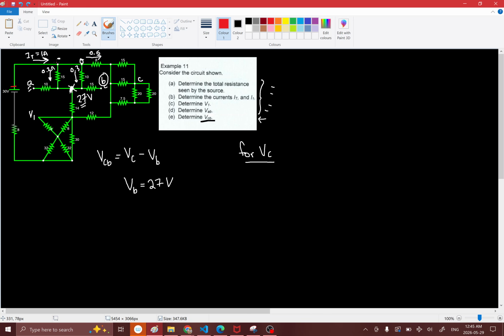All the current, which is a lot of current, can't just go through one resistor, so it will split itself among 2 or 3 resistors, that's fine. But when the current goes through this resistor, it has the option of going down this network of resistors, or it can just go down this freeway, which doesn't have any resistors. It's all going to go down this freeway, like that.